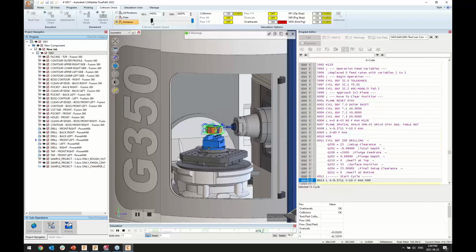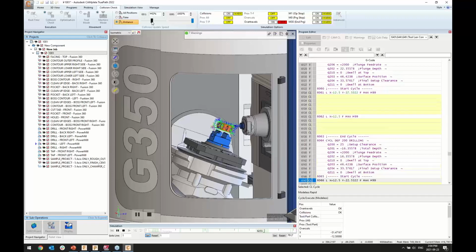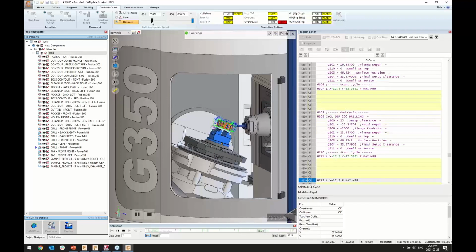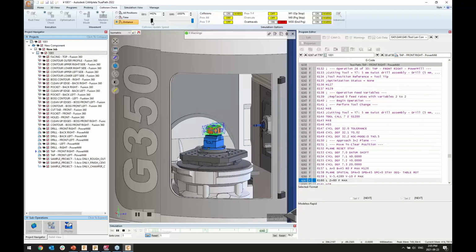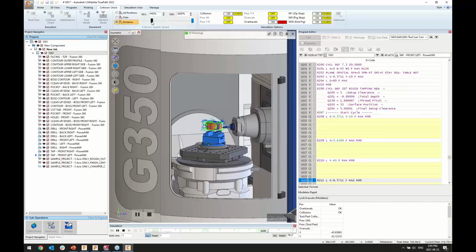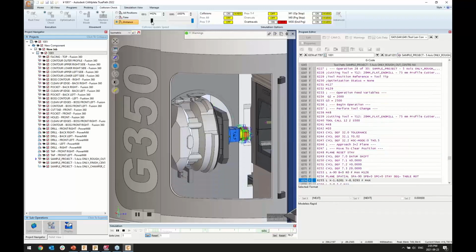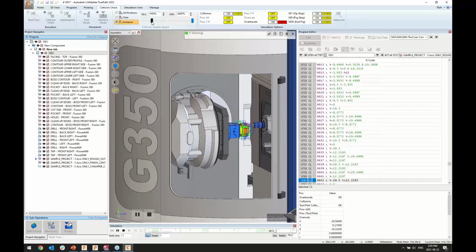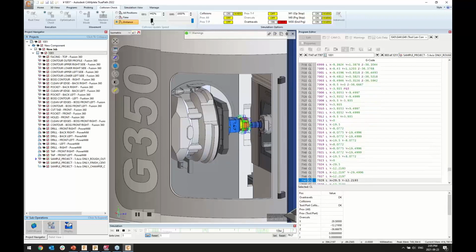We've accommodated a very large number of different machine kinematics. So at that point, the CAMplete team has really provided the framework to develop those. We'll be providing the initial draft, or the first go, on the post-processor, but would there be any changes needed? It's a little bit of a case-by-case scenario. If it is something that can be handled at the post-processor level, for sure, the team will be here to help you support that. Because of how the post-processing is handled, specifically in toolpaths, some of those functions are handled within the software directly, not at the post-processor level, but really within the architecture of the software itself.